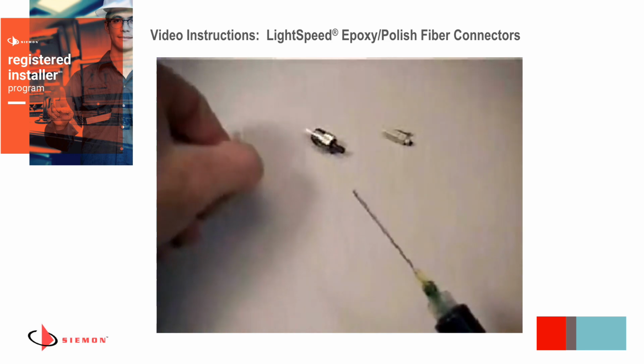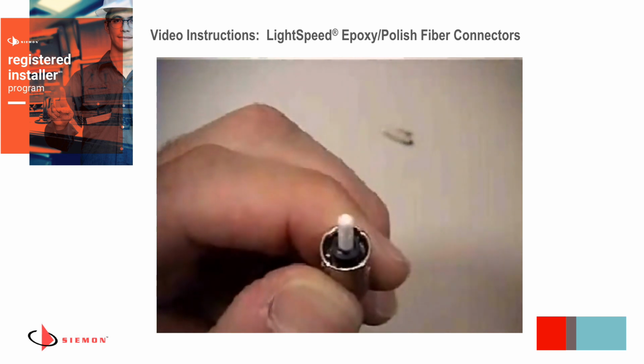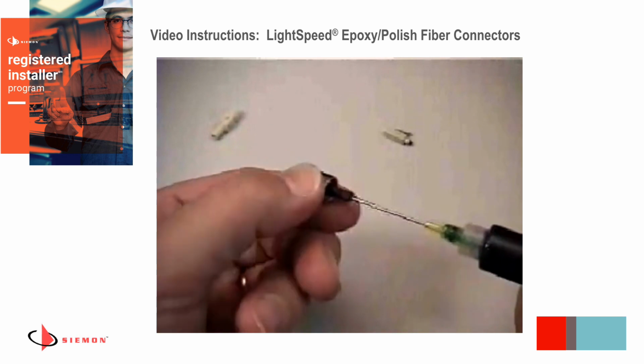Also inject a small amount of adhesive into the back end of the connector. This ensures bonding of the buffer to the connector, strengthening the termination. Be careful not to overfill, to prevent a backflow of adhesive.